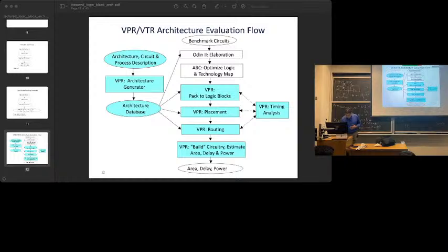The last thing is that these algorithms basically adapt to what the architecture is. Quartus and Vivado have a certain number of architectures built into them, and they know how to optimize very well for those architectures, like Arria 10 and Versal and so on. VTR is a bit different. You give it a human readable architecture description.